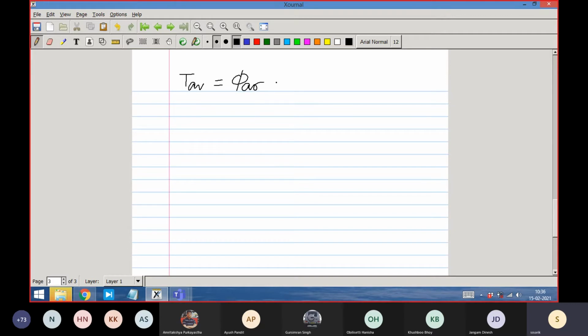Obviously, to make it more clear, peak. Understand this as peak, and then MMF of the rotor peak, and the sine of the angle between these two peaks. In the space they are sinusoidally distributed. This is the sine delta R. So now from here I have given you the equation. Then how do you construct a machine? Who decides this phi AR? Who decides phi R? It is still very vague.